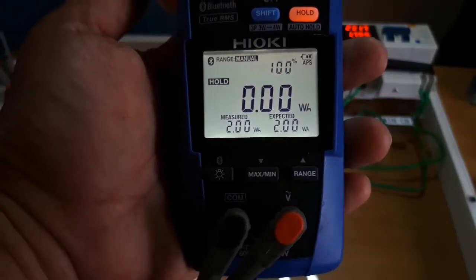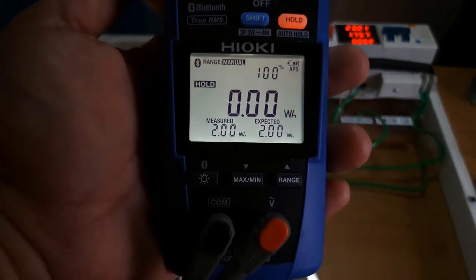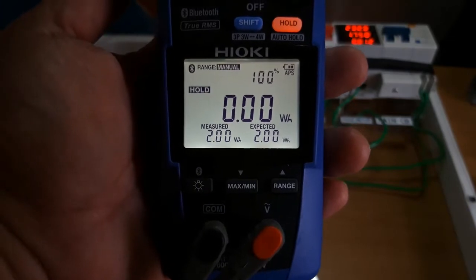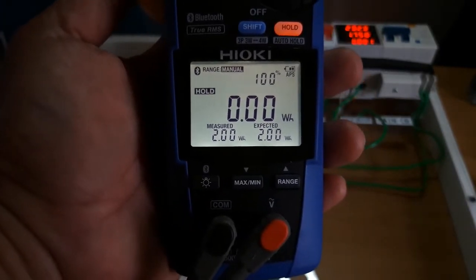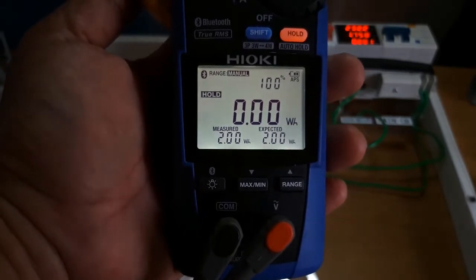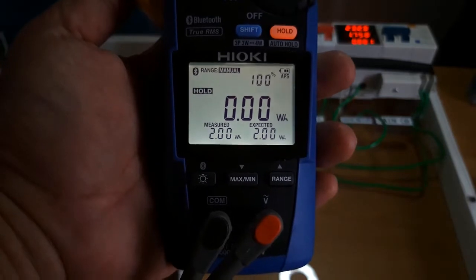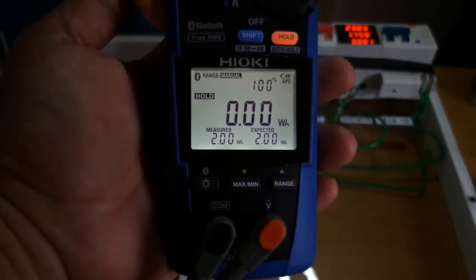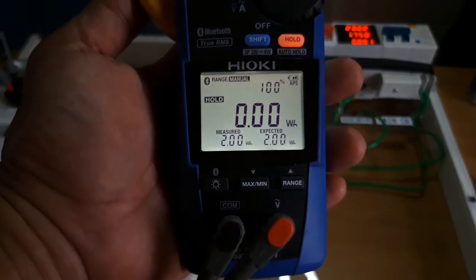So that's it. It means that the energy meter is functioning properly. For this measurement, I'd like to point out also that it doesn't matter if you begin measuring at the first pulse and stop measuring at the second pulse, for as long as you begin and stop measurement on two consecutive pulses of the energy meter, that would be fine.